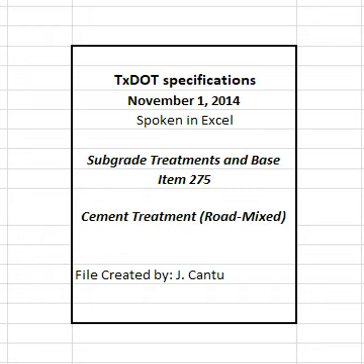Shape existing material in accordance with applicable bid items to conform to the typical sections shown on the plans and as directed. When shown on the plans or directed, proof roll the roadbed in accordance with Item 216, proof rolling, before pulverizing or scarifying existing material. Correct soft spots as directed. Provide the borrow source location well in advance when material is imported, to allow time for testing and approval to avoid delay to the project.